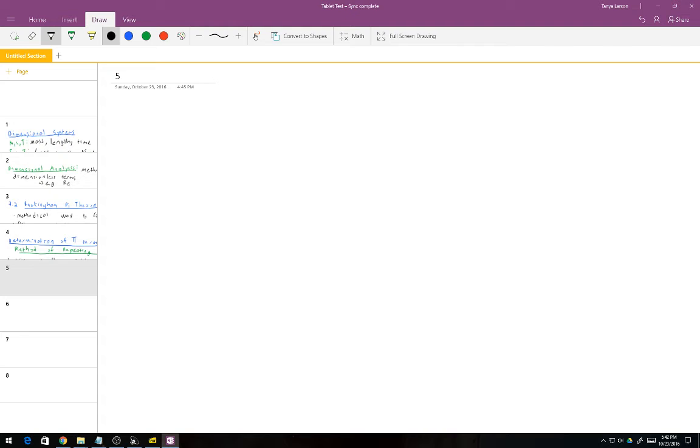Then for pi 2, well, let me start with mu, which has dimensions of L to the negative 1, T to the negative 1. Then I'll divide by, because mu is going to be my non-repeating variable, so I just want to start with it. It's going to be the non-repeating variable for this pi term.